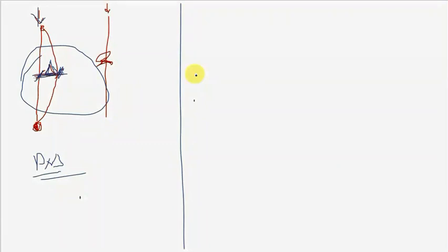From that you can get your slenderness ratio and check it against the slenderness limits given in the codes to know whether it is slender or not. If you prove that it is a slender column, then you have to design for additional moments. So apart from the original moments acting in this column due to the gravity loads or wind loads, you have to design for additional moments caused by the deflection due to buckling.